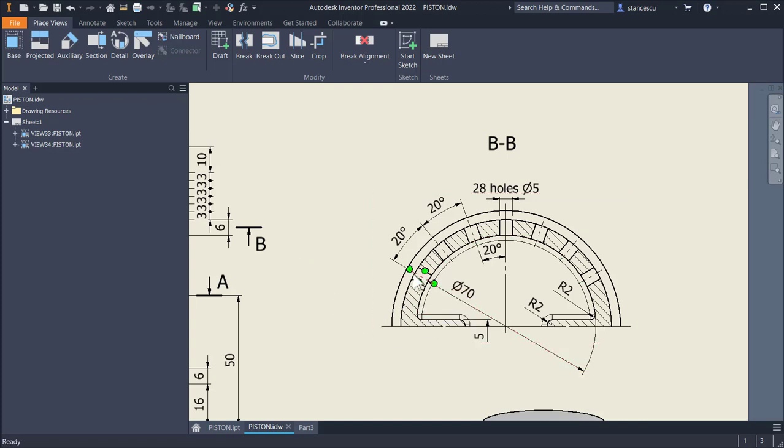How to create this first axis, to create the first hole, and then to multiply on a polar pattern or circular pattern, we create a plane, we intersect with another plane at a certain level, and then we have an axis.